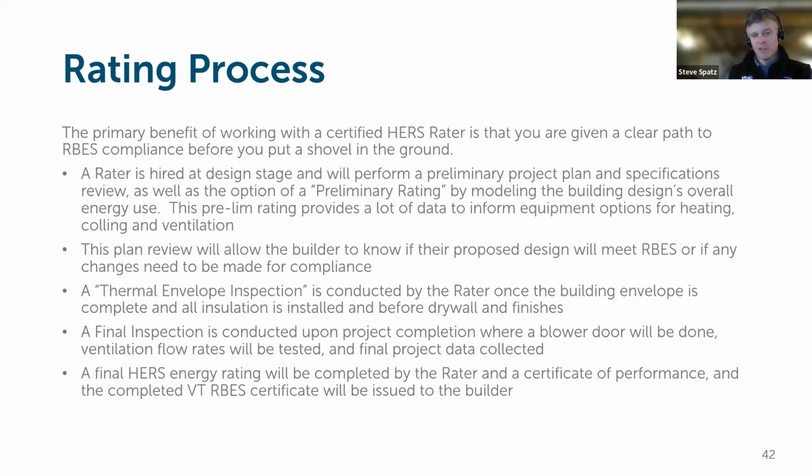And it can provide some really good data to guide some of the mechanical equipment choices along the way. So ideally, again, there's that preliminary rating. The HERS rater is required to come in and verify the thermal envelope before the building shell is closed up with finishes. So this is part of the process. This is a third-party verification of code compliance.